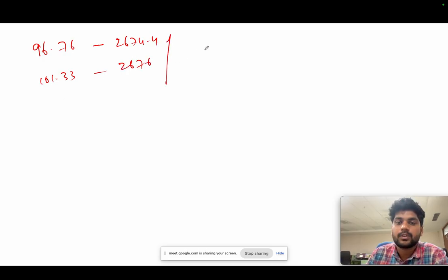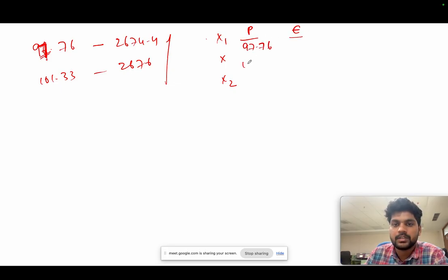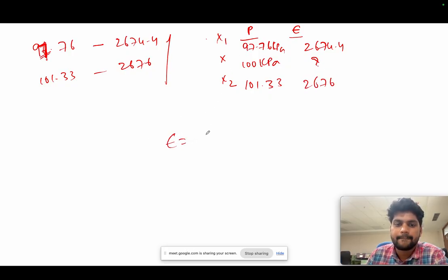So now how you will calculate is, take it as x1, x, x2. Sir, it's 97.76. Okay, sorry, 97.76. So now take it as this one. So the pressures and the enthalpies you have. The pressure one is 97.76. You need to find out at 100 kilopascal, and the new value is 101.33. The enthalpies are 2674.4. This value you don't know. It will be 2676. So the desired value will be x2 minus x divided by,